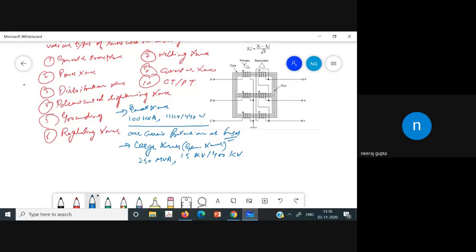However, if we use overcurrent protection in the form of fuses for this transformer, it is not sufficient. We need an elaborate protection system for that. We need different types of protection systems. We need the differential protection. Then we need protection against internal faults, incipient faults.